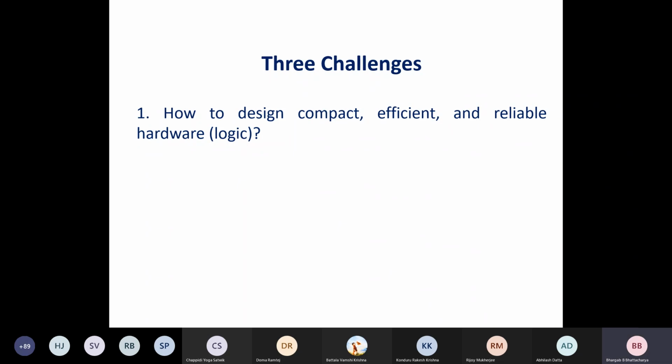Now just imagine this scenario that you have a small chip, a small processor whose area is very small, where so many transistors have been compacted, and each of them is pulsating at a high frequency, changing the state between 0 and 1, 1 to 0, and so on. Therefore, they will dissipate an enormous amount of heat, and the chip might burn out. So it has to be power efficient, it has to be energy efficient. At the same time, it has to be speed efficient. Okay, so there is a trade-off between delay and power and this kind of thing.